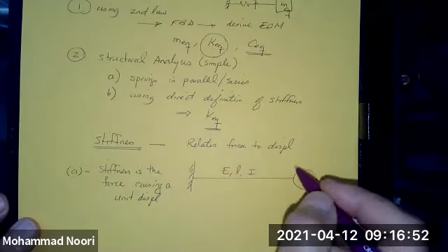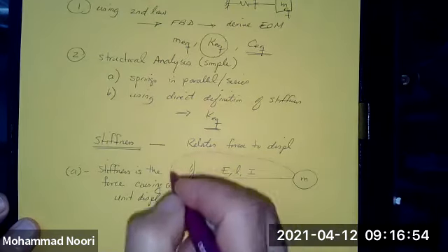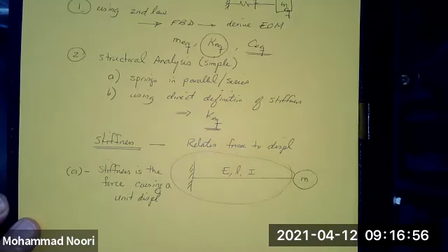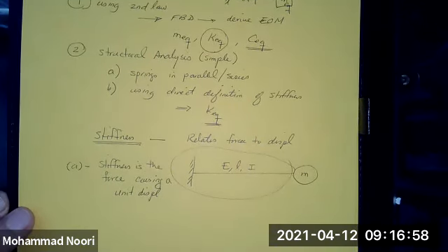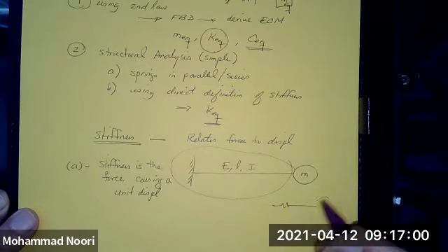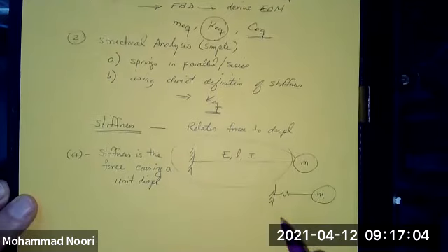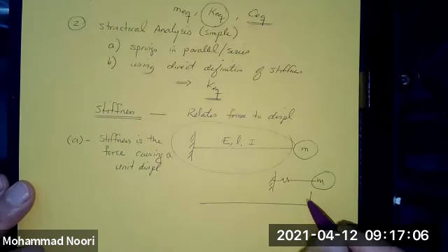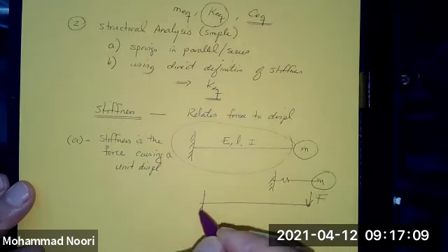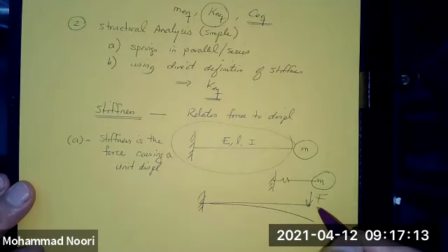Okay, so what is resisting the displacement of this mass here? If I want to find an equivalent stiffness, which is resisting this mass here, which is the stiffness of this beam, I say, okay, this beam under the action of a force at that degree of freedom, that's what we're interested in, right? Which is the tip of the beam.